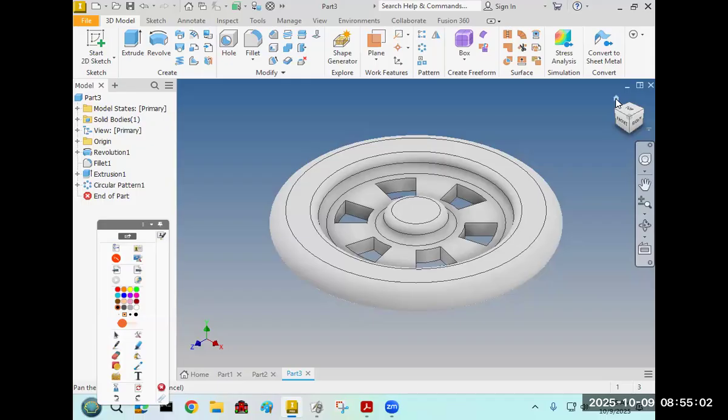Do extrude, which gives you the cut. That's fine. As you're cutting, look at the corner and make sure it's going in the same direction. Okay, and then circular pattern, which is this dotted circle right there. First thing you have to tell it is what features to pattern, which is the cut, that's the first click. And then the second click, you get the cursor for rotation axis. Put the cursor down. What rotation axis, anything that's right, yep.